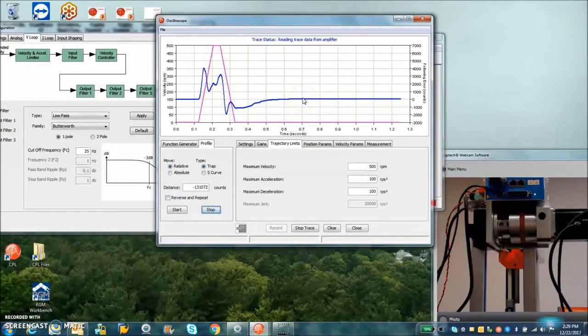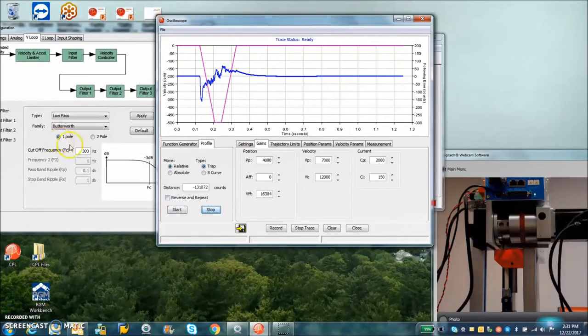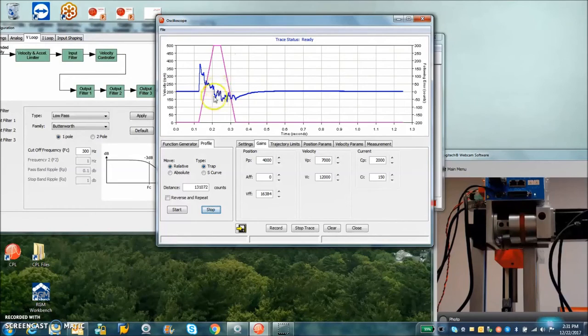So this feels very well behaved, no big jerking, just normal tuning and settling. Okay, so here's with the pole at 300 hertz, single pole, high gains, and this is rather well behaved. I think I like this tuning a little better. If there's a disturbance based on the mechanical system, we have gains to make corrections.